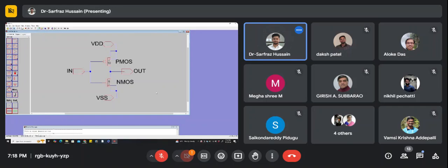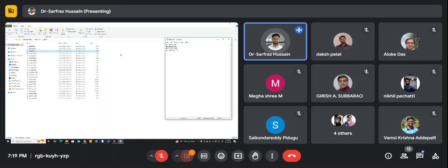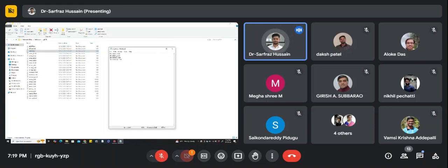Now we have not called upon any of the technology file here, right? So we need to call upon the technology file that we are considering. This one is GF180, so GF180 PMOS and GF180 NMOS. So now what we'll do is go back to our previous folder. We'll go to this GF180 nanometer, and here you can see there are a lot of file definitions. Here all the SS and FF, which talk about what is SS and what is FF. So we click on this one, all the 4 T's will be there. Once we click on that one, you can see here in this particular folder.